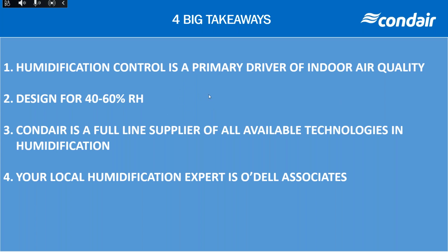How do you keep RH 40 to 60% in hospital bedrooms and laboratories? I can take that. We need to look at the sources of ventilation air or outside air that are coming into the space, which would be the amount of dehumidification happening, and which brings in low absolute humidity, and be able to offset that by delivering either steam or adiabatic humidification into the duct air handling system to deliver that moisture to the space.